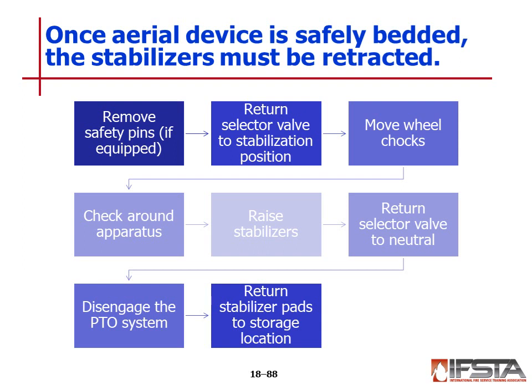Once the raising procedure is complete, return the selector valve to the neutral position and disengage the PTO system. The driver operator should return stabilizer pads to their appropriate storage locations.